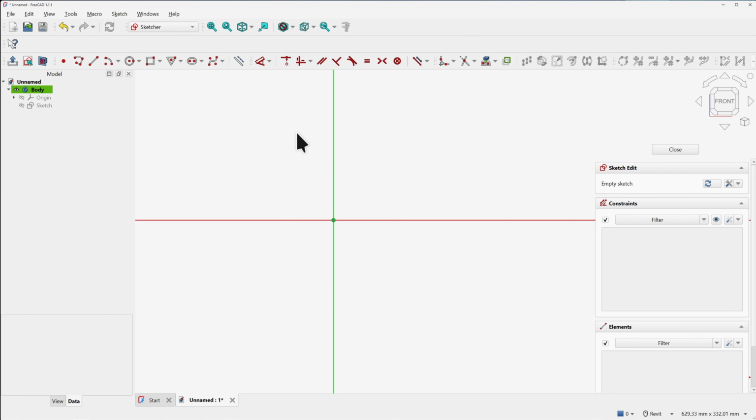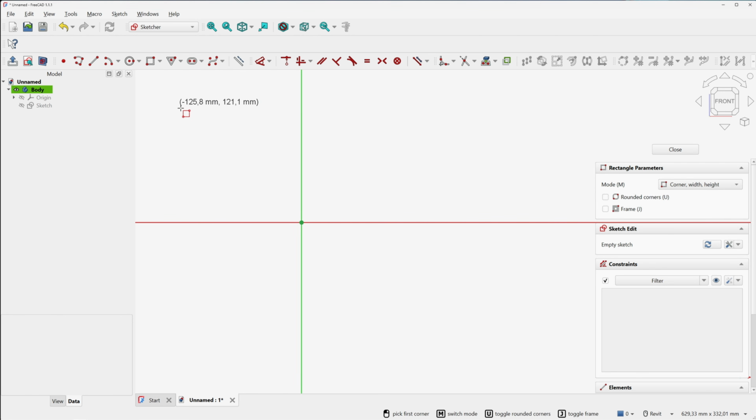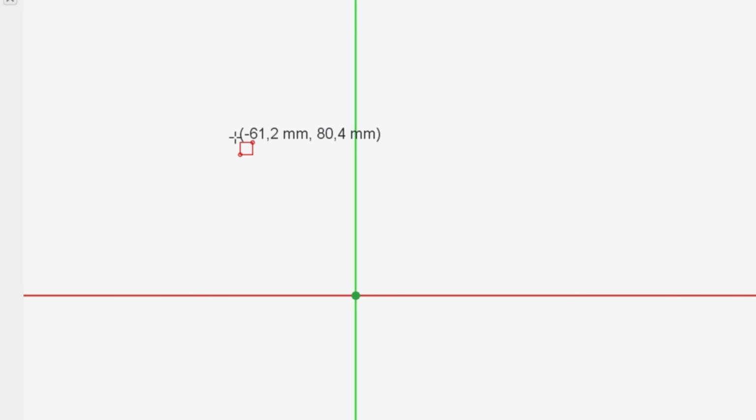What makes the Sketcher so powerful compared to a simple drawing is the ability to link your lines together by applying constraints. In the toolbar, the icons with white lines and red points represent the drawing tools, while the ones in red are the constraint tools. The strategy is simple. We're going to create geometries and then constrain them. For example, we'll create a rectangle. Click on the rectangle tool in the toolbar. Near your cursor, you should see the shape you are about to create appear.